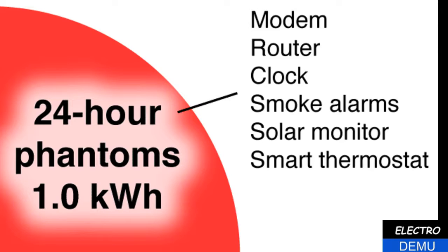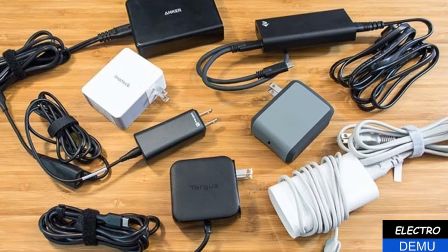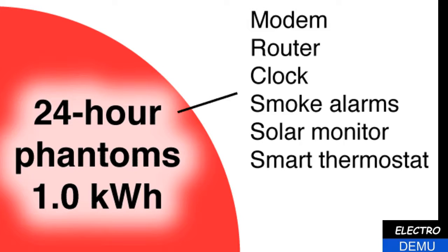Anything that you stick on the wall, even a laptop supply cord that's not even hooked up to the laptop. Just leaving it on the wall, the transformer itself, the primary circuit is still running, and it's kind of like drip, drip, drip because the power source here is very low, but because they're on 24-hour, they add up because